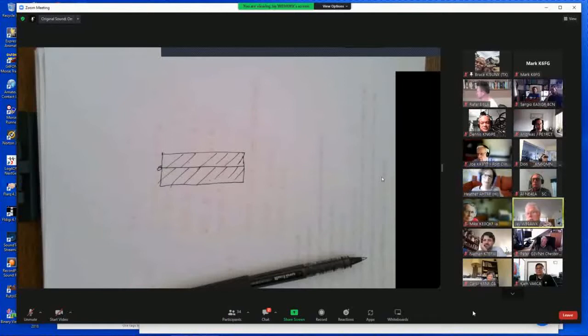Now, what you could be having is a couple of things. One is you're getting interaction: the signal's coming in and it's overloading the front end of your radio. It's just absolutely hammering the poor little transistors at the front of the radio, and you might be generating all kinds of different products. You also might be getting mixing, where two signals beat together.